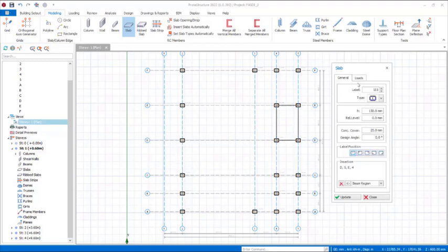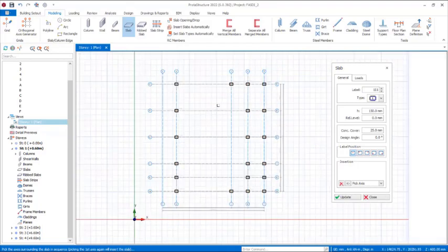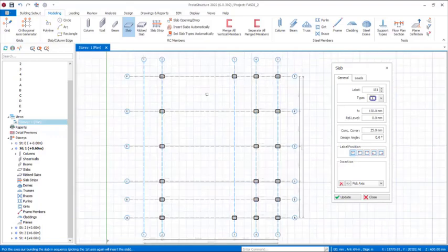We come to the general tab again. We have to insert the slab using this thing. We will be considering the insertion options, pick axis insertion options. So here is the pick axis insertion options because we want to be inserting the slab panel by panel. All right, so we use the pick axis to insert it so that we design it using a finite element analysis method.